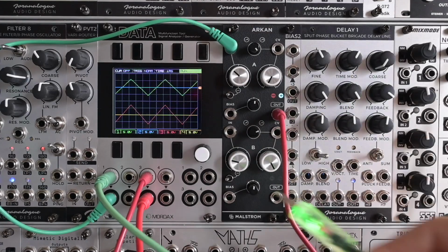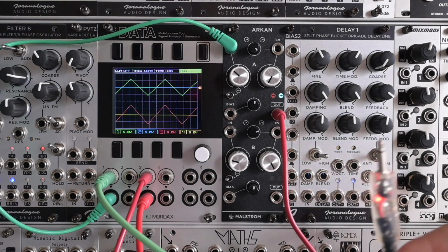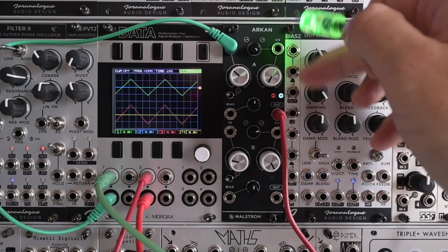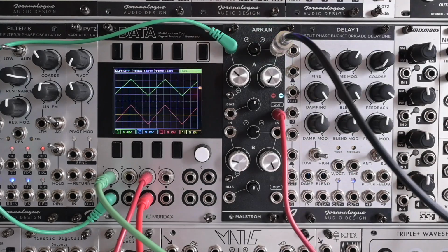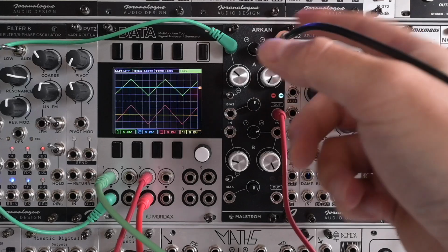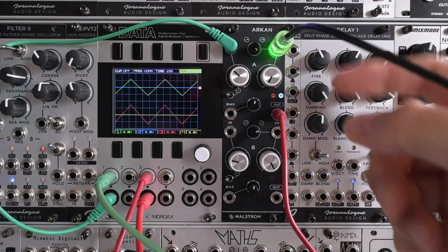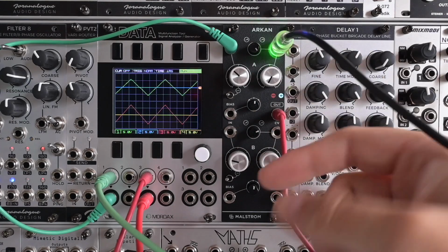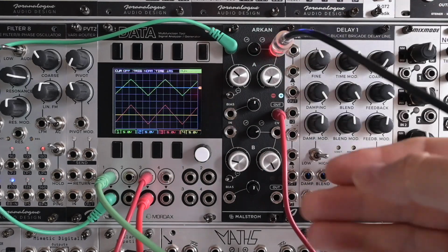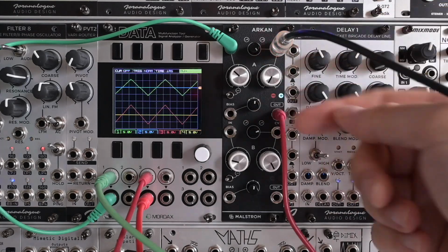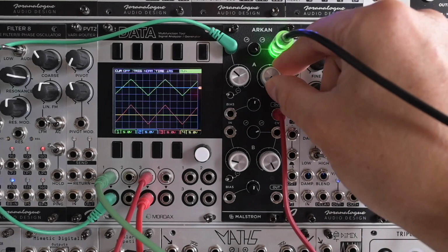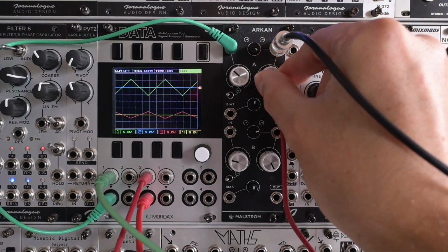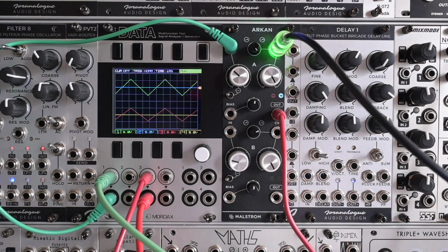Now let's use this slow moving triangle LFO, which is bipolar by the way, to modulate this parameter. And again, nothing is happening. Well, that's because as soon as you send a signal in to the CV input here, the operation of this attenuator kind of inverts to, well, what you would expect, being completely closed when it's to the left and completely open when it's to the right. And now we are seeing a 4-quadrant multiplier.